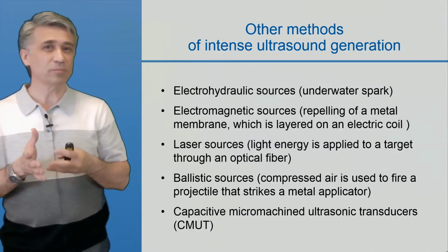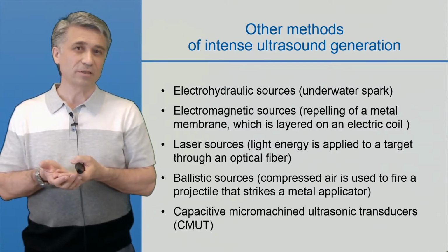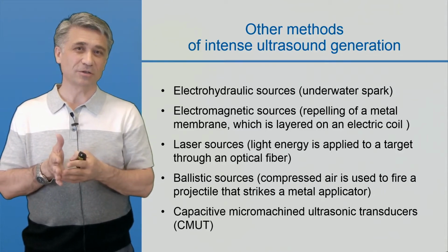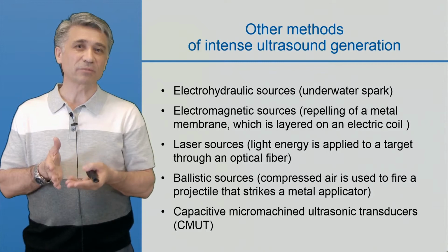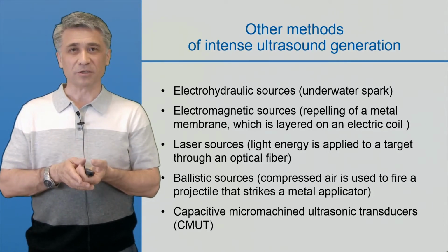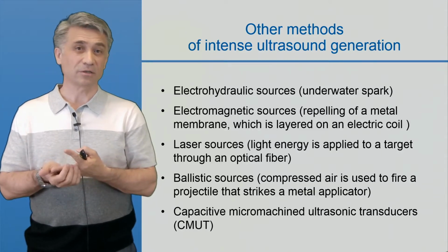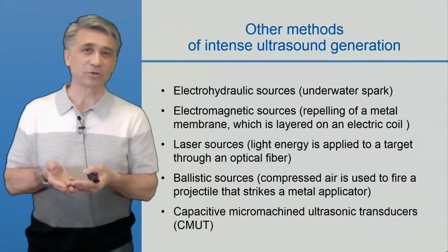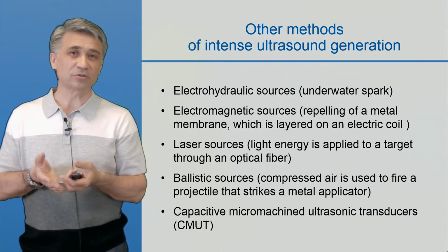For instance, those pulse sources are used in lithotripsy. This is a procedure where short, intense ultrasonic pulses are used to fragment kidney stones. But not only pulse sources can be created in a non-piezoelectric manner. There are also continuous wave sources, which are called capacitive micromachined ultrasonic transducers, CMUTs.